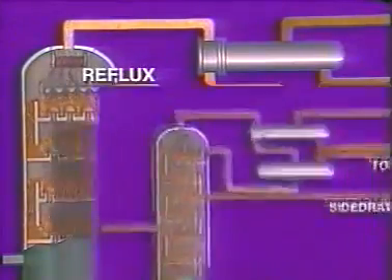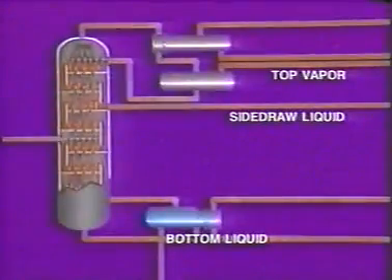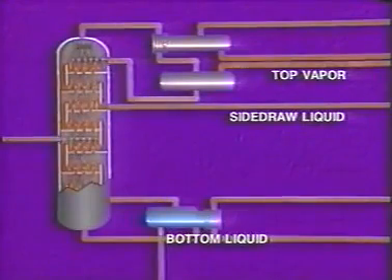This fractionator is similar to the distillation tower we showed. A specific pressure range must be maintained inside the fractionator because an increase in pressure will increase the boiling point of the liquid feed. Any change in boiling point changes the rate at which various liquid components vaporize. So a change in fractionator pressure could produce too much of some products and not enough of others.